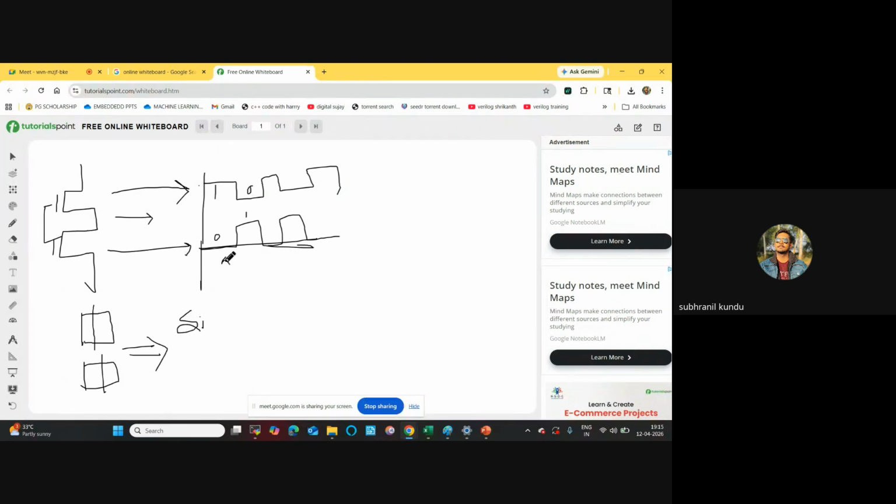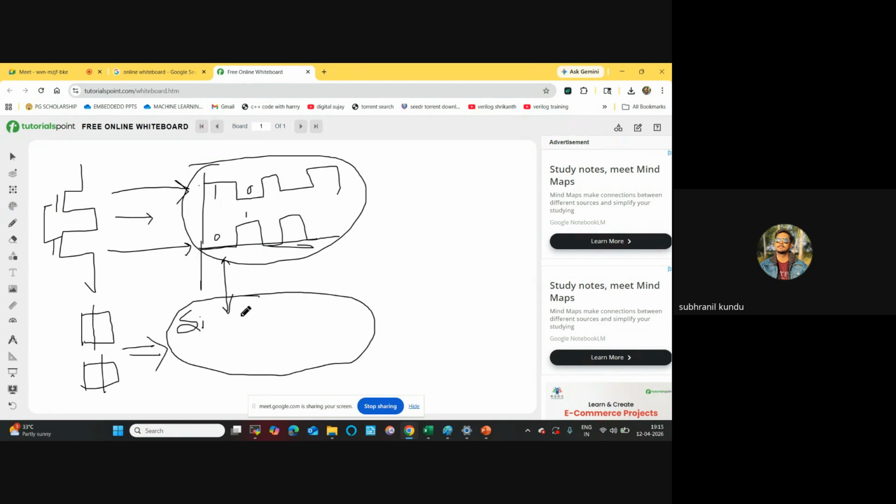There will be two data: this design waveform and this simulation waveform after layout. They should be exactly matched. Only then will it be called a perfect layout. Otherwise, your layout is not good. If it is not matching, delay can come, for example due to routing parasitics. This is not acceptable, so you need to do the perfect layout.